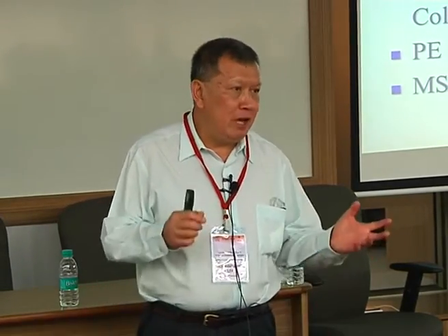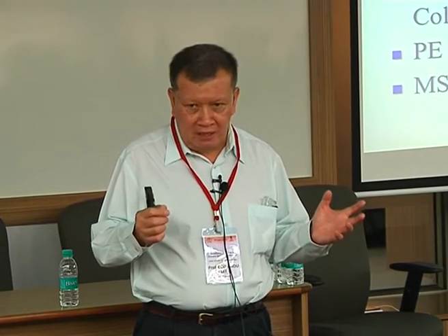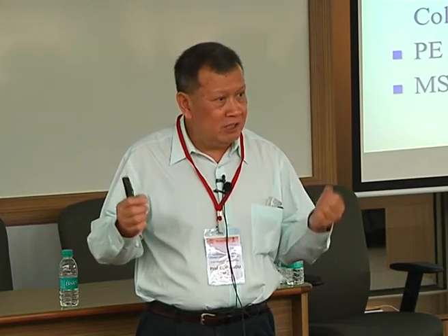Just to give you some idea of the engineering properties of this clay, the undrained shear strength will range anywhere from 15 kilopascal to 25 kilopascal. That's the kind of undrained strength. So it's pretty gooey stuff. Right? The permeability is very low, 10 to the minus 9 meter per second. The plasticity index is typically 50 to 55. So it's just a high plasticity inorganic clay.